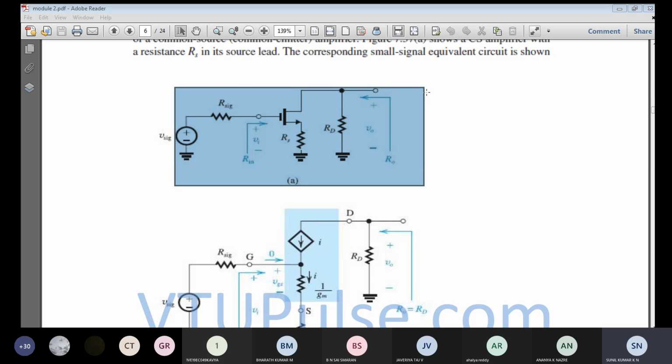So this is the modification. Since between drain and source one current source was there, now I am going to add another current source in series, and we are going to insert one node X. This is the slight modification. So whether this model and this model are the same? Yes, this is also the same, and this is also the same, because the terminal current characteristics and voltages are not going to change anything. So this model is also the same, and this model is also the same.